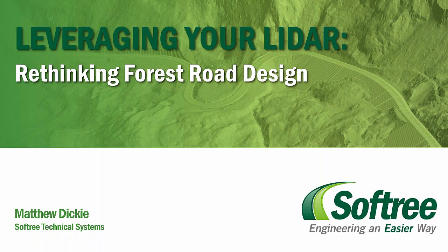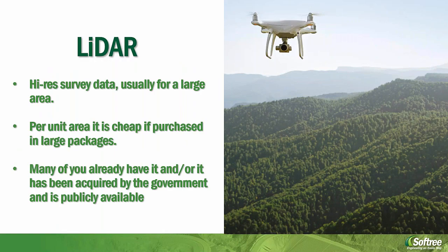So our topic is using LiDAR to improve forest road construction. So we kind of have to cover what LiDAR is. All it is is high-res survey data. It's usually collected for a large area, usually collected aerially by fixed wing. Drones are becoming more popular now, so you can scale it down and have smaller packages done with the drone.